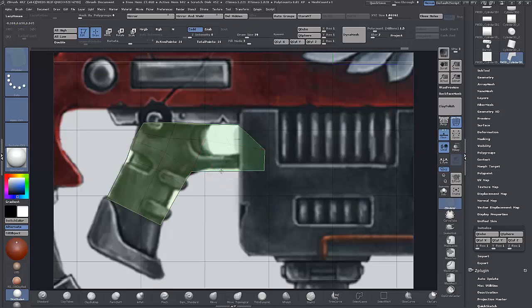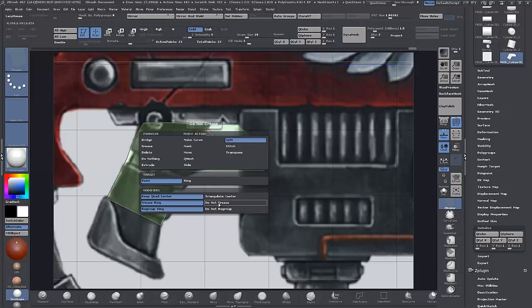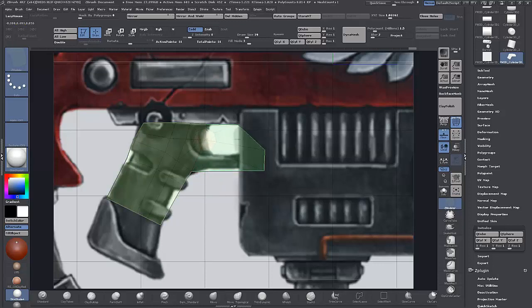I will leave that for the moment. I'll just put one in here, and now we can split that. Do not crease, and we'll split that to the size we want, and now we'll select these, same as we did before. Hold down Alt and delete hidden. Yeah, that should be okay there. Delete hidden, and now we'll start to manipulate the mesh.